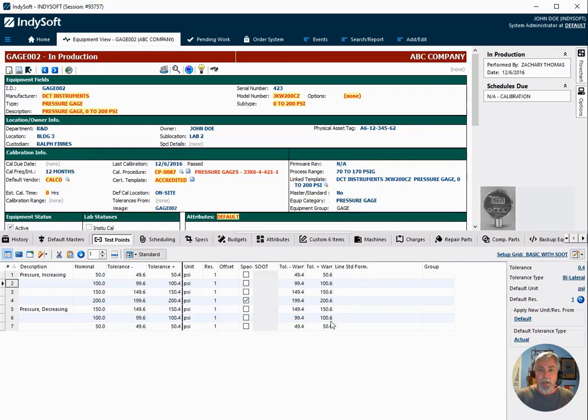Trying to do that in your head a lot of times, especially when you're in a production environment, can be rather taxing and rather difficult, and a lot of times it might not happen. So what we can do is use the significant out of tolerance flag to do the same thing as the out of tolerance, but we tighten those values down so that it now becomes an optimization flag.